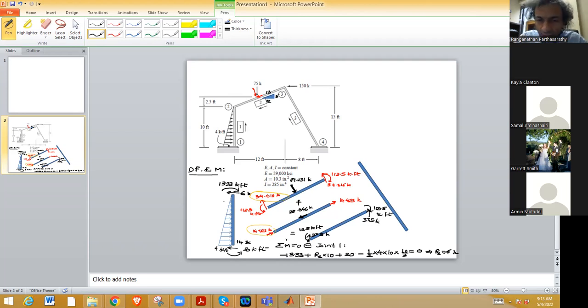Okay, sorry. So here are the reactions: 37.5, 37.5. And the moment. So we got fixed end moments and reactions for, you can confirm. So if you add up the components of this: 34.616 times 12 over 13 plus 14.423 times 5 over 13. So we got exactly 37.5. Okay.